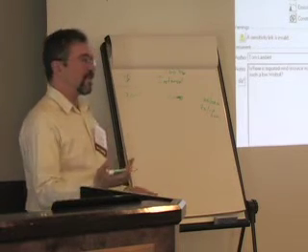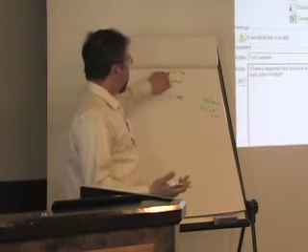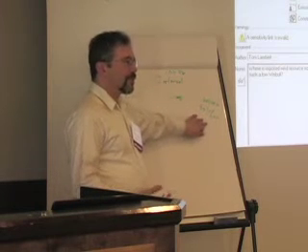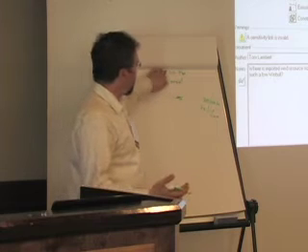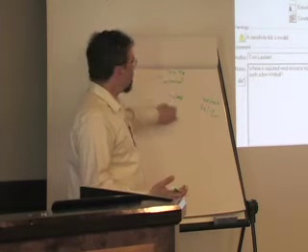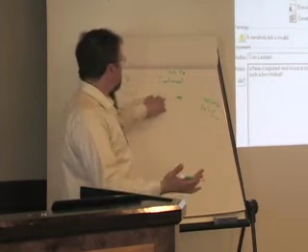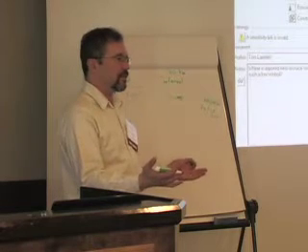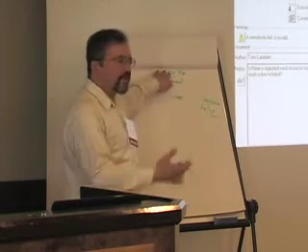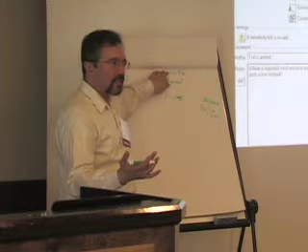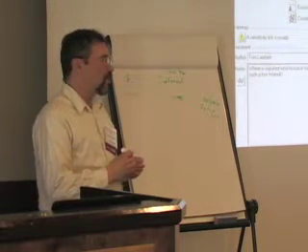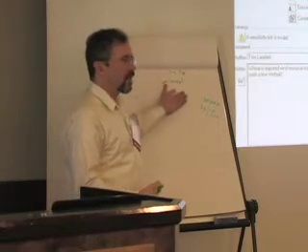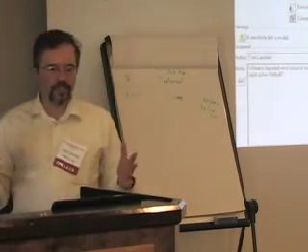If you wanted to convert that to cents per kilowatt hour, well, how many kilowatt hours are you going to produce in these 100 hours? If you're operating at full capacity, that'd be 10,000 kilowatt hours, that would be 3 cents a kilowatt hour. But you're not going to be operating at 100 kilowatts the whole time. So how do you calculate cents per kilowatt hour?